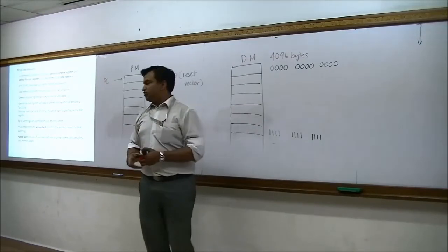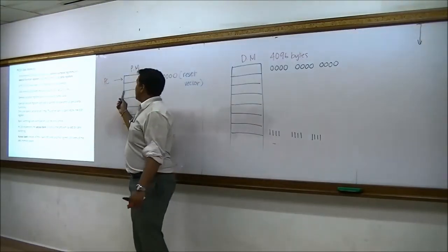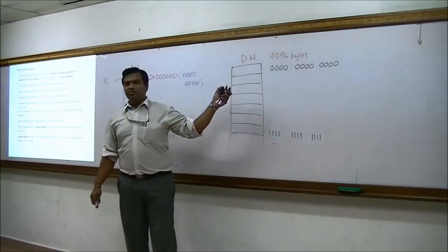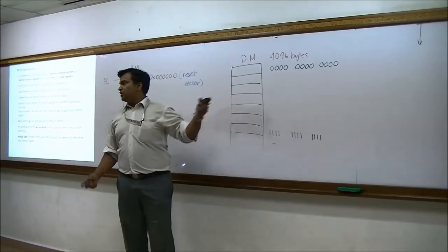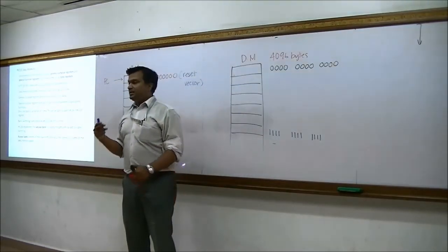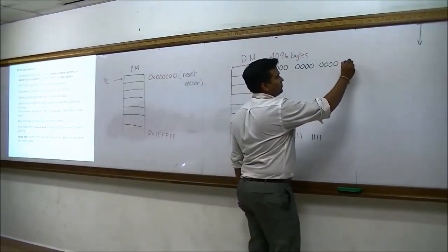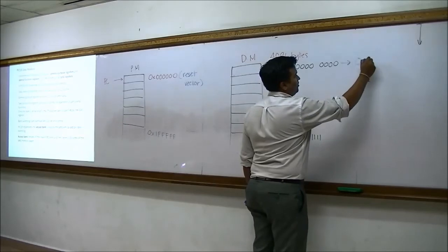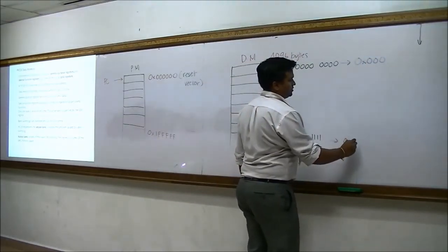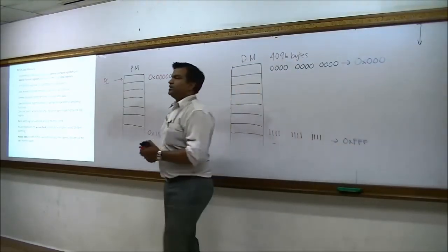When you convert this, it is the same concept. The limit there is 2 million, so you get 21 bits. This is 4096, so you get 12 bits. You require 12 bits to address each one of them uniquely in the binary system. Of course, we would like to represent this in hex. So this one becomes hex 000, and this one becomes hex FFF. Is there any question?